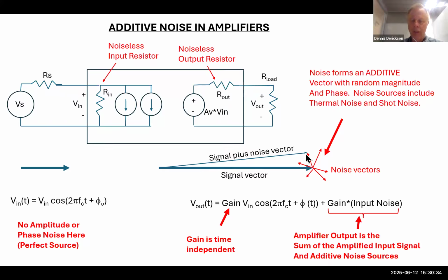So sometimes we have FM or phase modulation, sometimes we have AM modulation, so it just happens randomly versus time. So an amplifier, even though it's not modulating the signal, we're going to view the noise as if it were just putting both AM modulation and phase modulation onto the signal, degrading its performance.